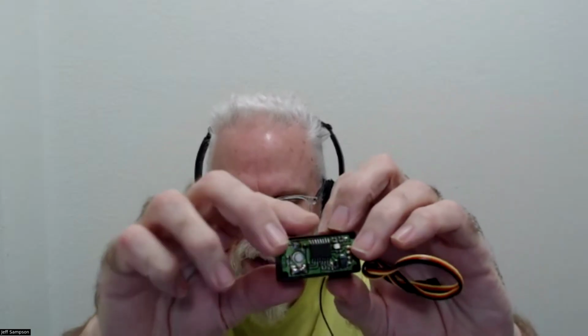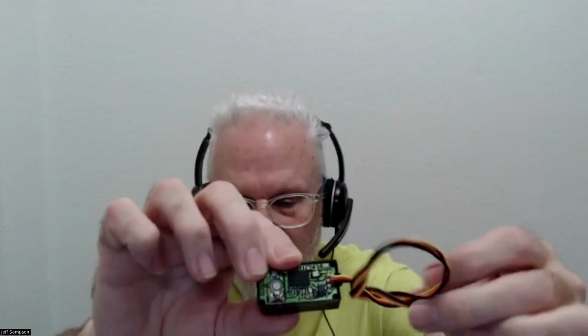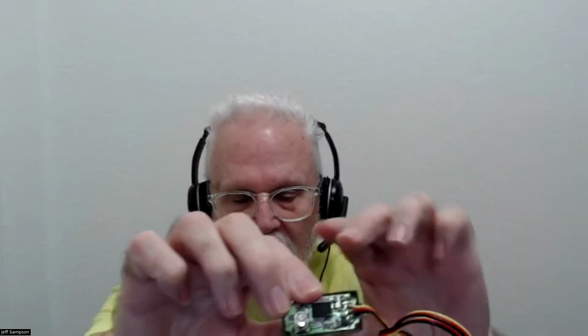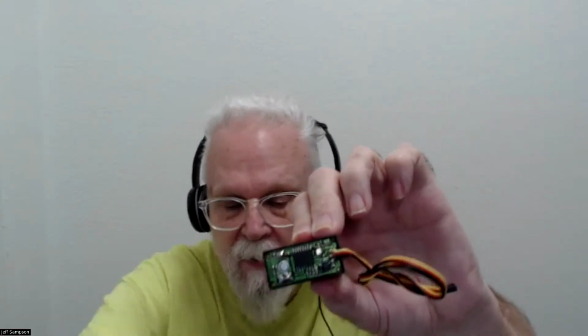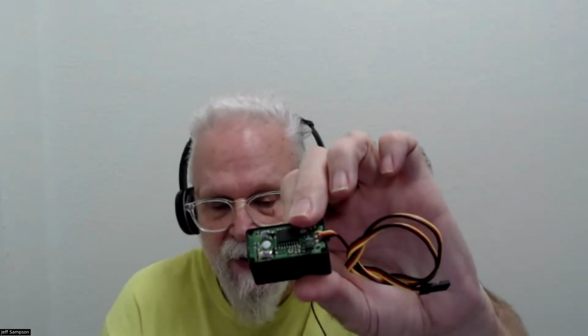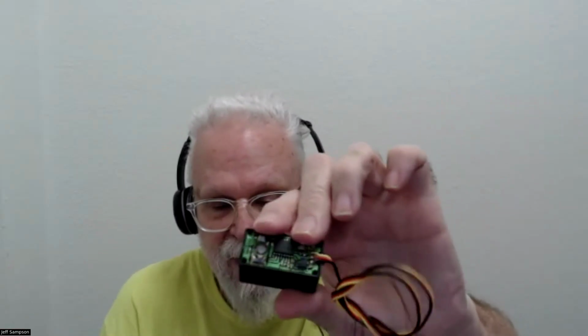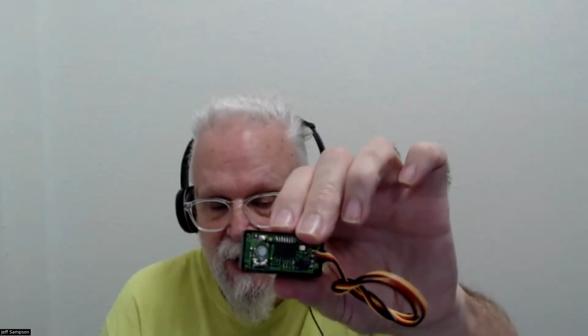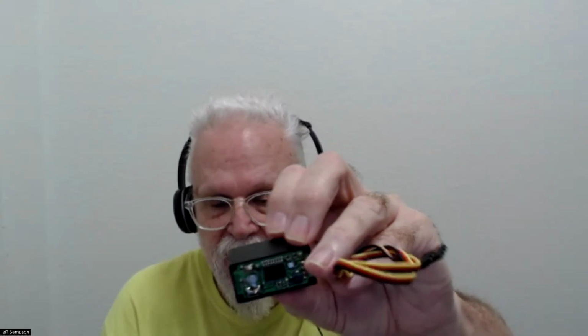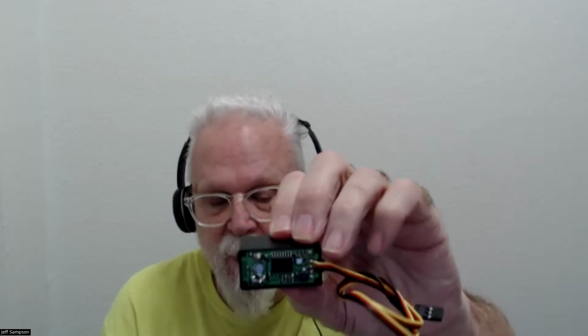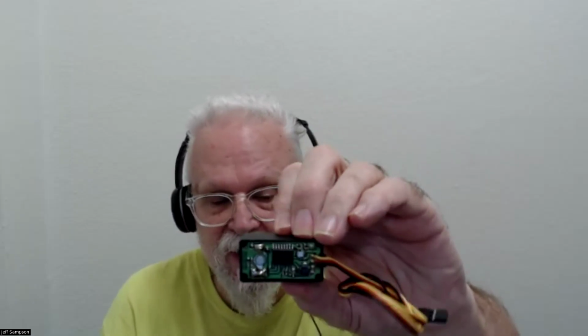But when you're done, you'll just have a flat printed circuit board. It's got your RC wires coming in here. And then the two wires that normally go to the motor, you just run those out, plug them into your motor driver board, and then hook it up to your big motor. Doing that should give you a speed control mode. So you run your RC and it runs your speed forward and backward at whatever your joystick is set at.